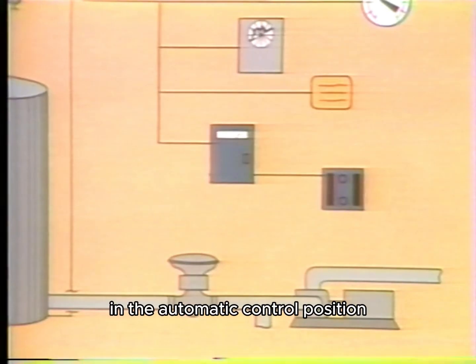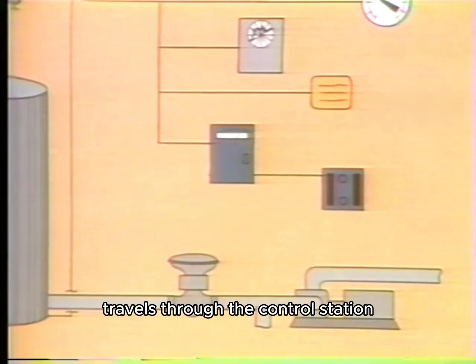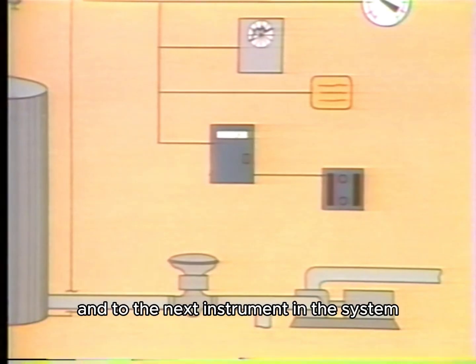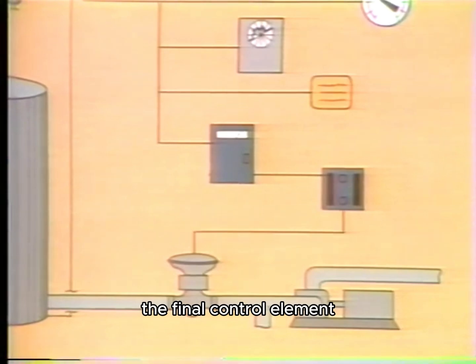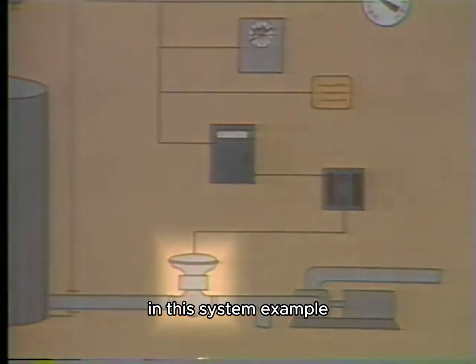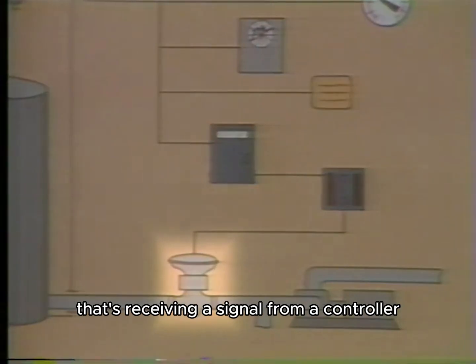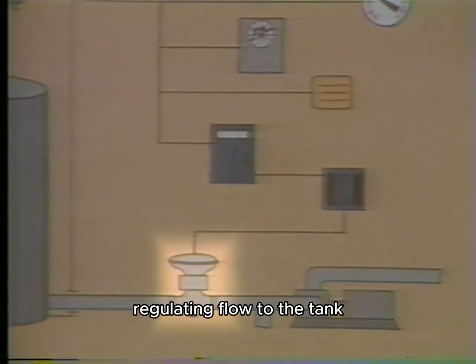In the automatic control position, the signal from the controller travels through the control station and to the next instrument in the system: the final control element. The final control element is a device that regulates the value of the process variable. In this system example, the final control element is a control valve that's receiving a signal from a controller, regulating flow to the tank.